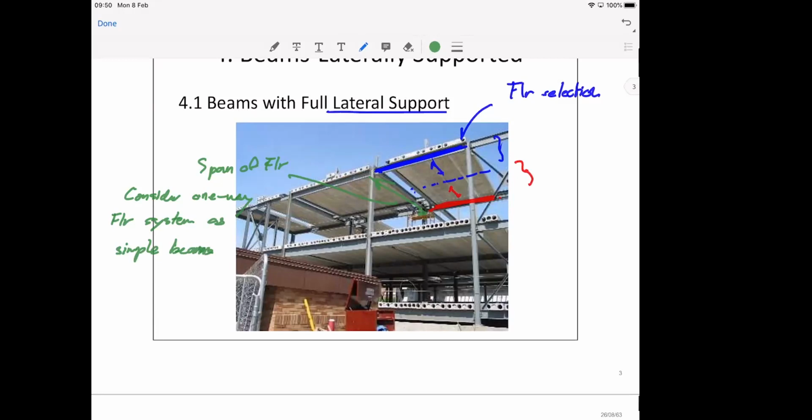Now in our projects, you see that you have a situation where the length of the floor is pretty short. So as long as you select the floor with longer span length, it should work for the shorter span as well, correct? And the width here doesn't matter. The width is involved with the construction and the availability of each piece of the floor.